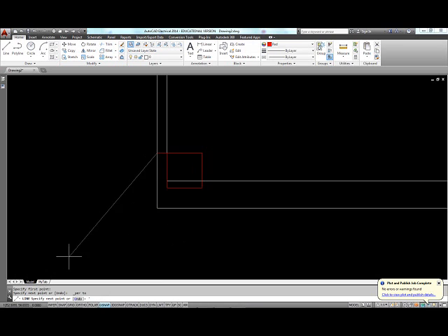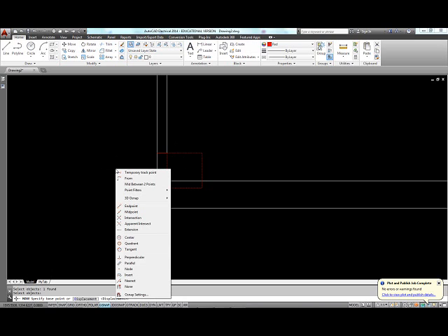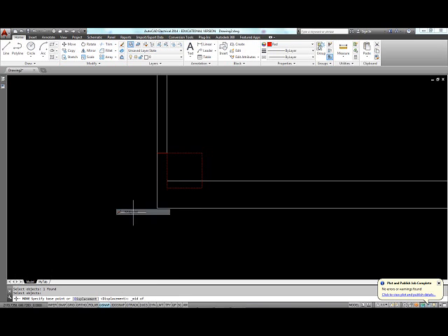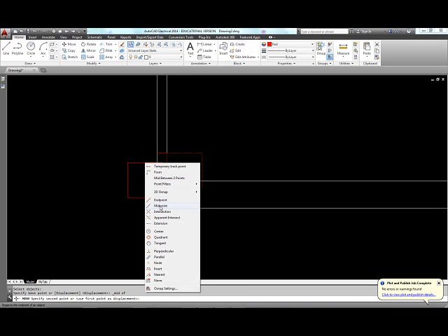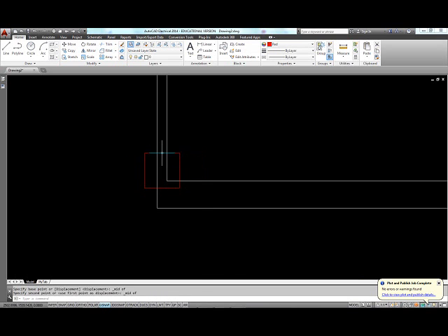Now escape, and I will move this object from, okay, choose, then spacebar from the middle, shift right click, midpoint, this midpoint, and then shift right click, midpoint again because it's not in the settings. There it is. Now choose this temporary line and delete it.